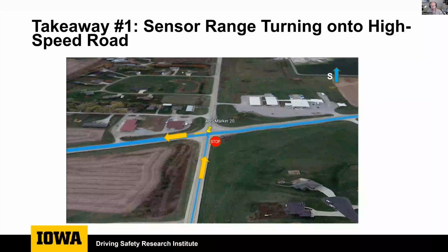So for our vehicle, our transit, that suite included things like cameras for detecting traffic signals, multiple LiDAR units, and 2 radar units. But for the most part, Apollo relies heavily, if not mainly, on that LiDAR data to detect and classify obstacles in the world. And it's that reliance and the limitations of those sensors that occasionally produced unwanted behaviors during a drive.